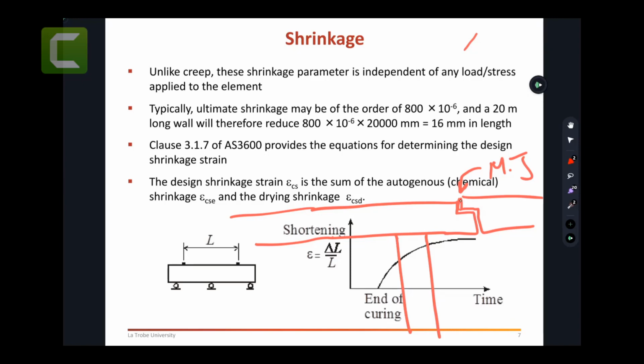And you would see, if you walk in a shopping center or in a car park, usually they put some plate on the top. You don't see that because they need to cover it from water, or they have to keep the slab, allow it to move. So remember, this movement joint is not only for shrinkage. I'm talking about shrinkage here because that's the topic. It's also used for temperature and other measures, because we need to allow for some movement due to impact, or if it's a bridge or whatever.